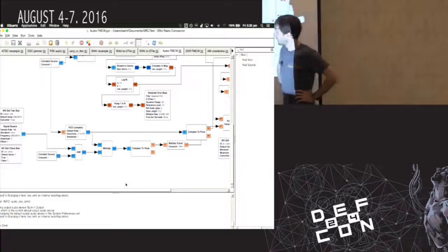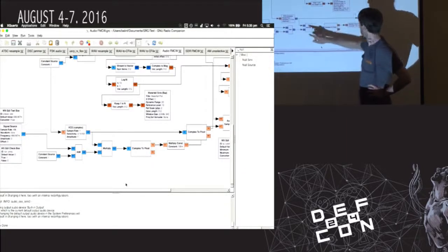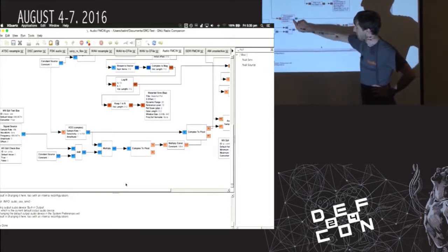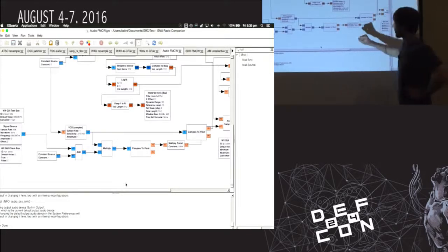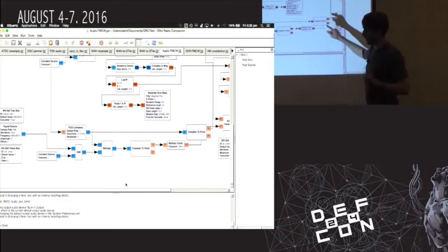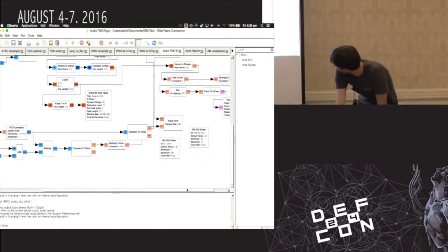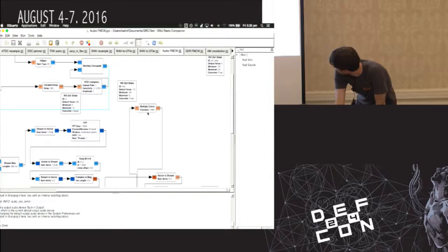And usually, since we're not running the array, we just take the output of this VCO, which is our chirp. But if we want to phase it, then we can do that too. So when we're not running the phasing, we want the same signal to come out the left and right channels of our speakers. So if we go and look at the audio sink here,